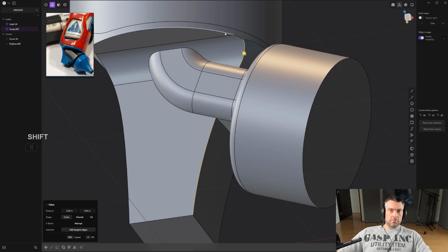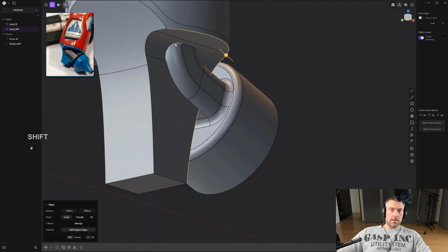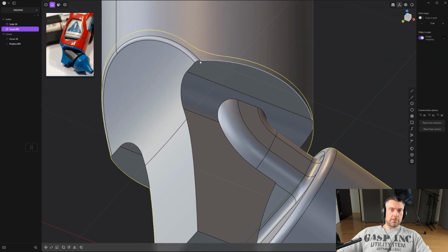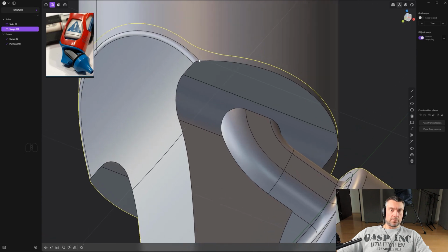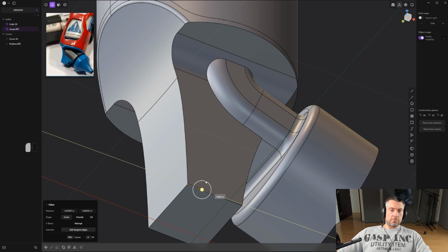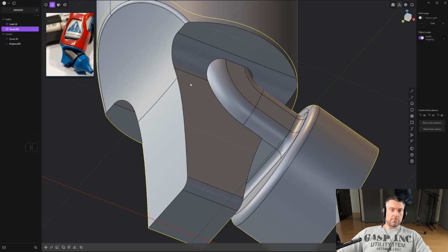Tiny ones also all the way up here. And before we run this one, we need to run this one. You see, there's an order of beveling, right? And it's very important to understand how it works. So first bevel here, then it's going to create a round transition. Then what we could do is actually run a bevel here as well, small one.